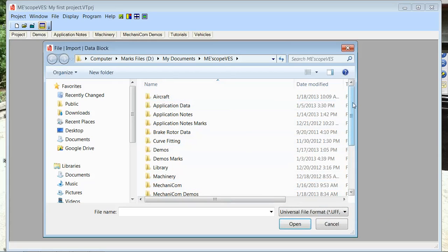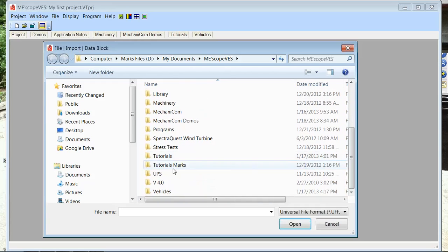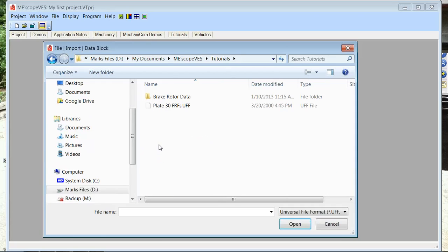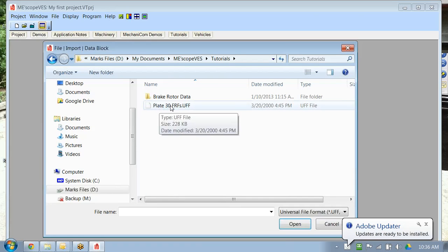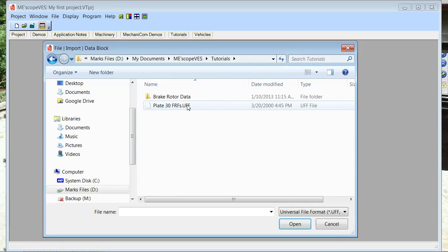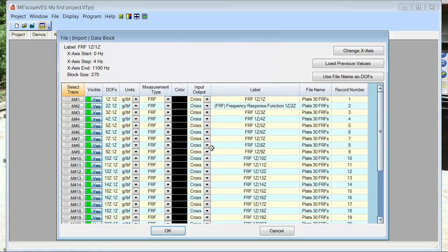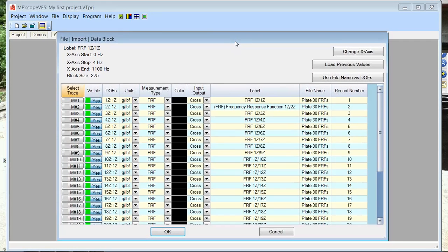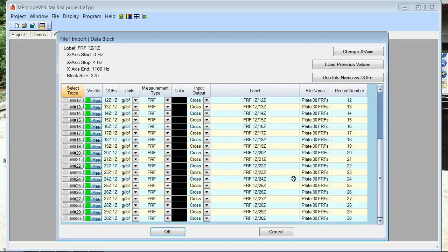Now we're going to use one of the drawing tools in ME'scope. Let me just right-click here, and we can look again through some of these menus, and you can see that a lot of them are talking about objects, a lot of these commands. So what do we mean by an object? Well, in the drawing, objects that we can have in a structure window are listed right here: points, lines, surface triangles, surface quads, substructures, and then a number of FEA or finite element objects that we can put on this 3D model if we're doing FEA work or SDM work.